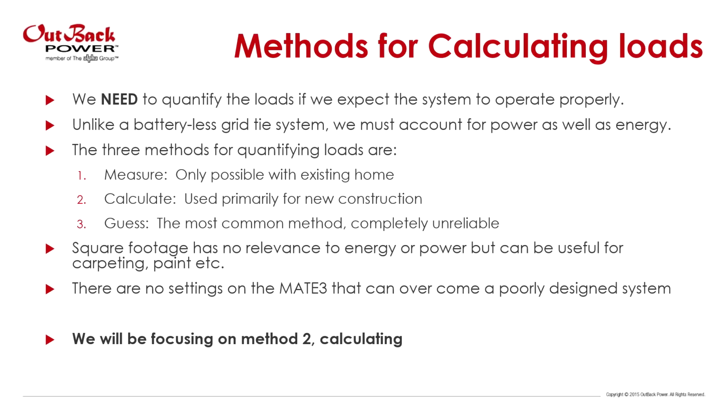So there are three methods for quantifying loads. The first method is measuring. When you get your power bill, it should really be called your energy bill because it's power over time. And this is actually very useful for battery-based inverter design. This uses actual data and actual usage history. This is the best way to get your load calculations.